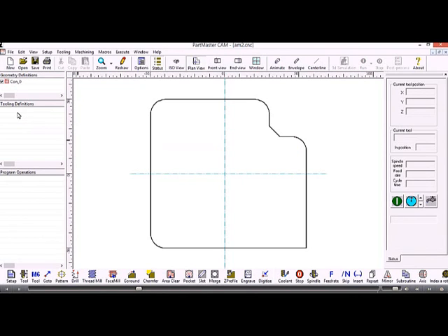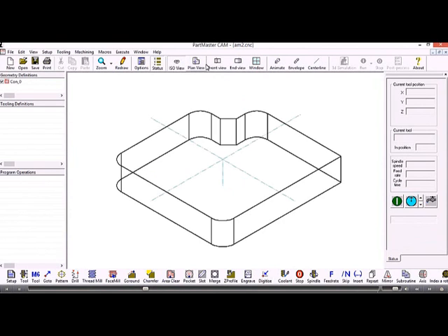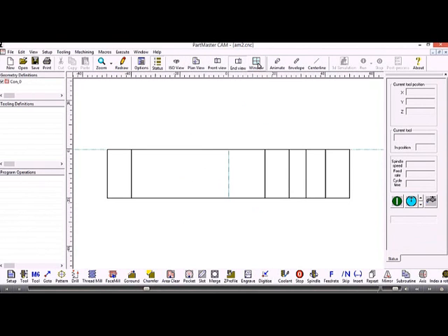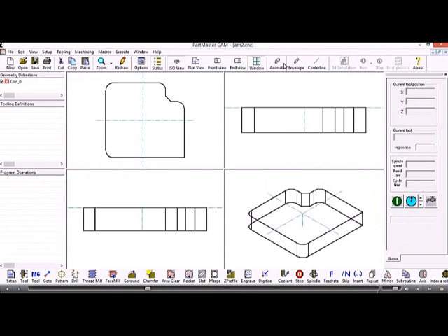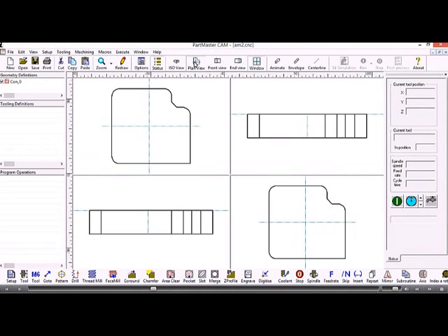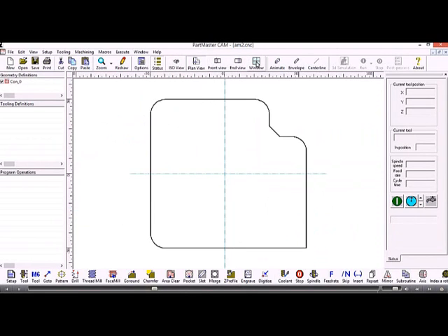We've got two toolbars at the top. The top one is the global operations, saving, opening and so on, and then how the screen is viewed. So this is where we set up the different views and then the different ways of drawing the tool path. We can use tool animation, tool envelope or tool centerline. So to start with we'll just go into the plan view and we'll switch off 4 windows.